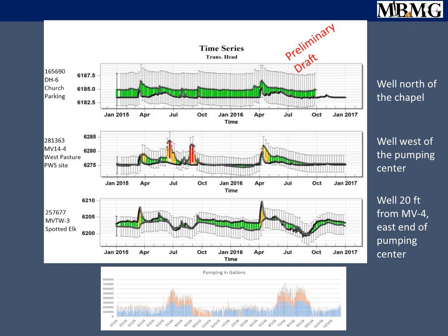Then down here in the lower one, you can see the impact of the pumping wells. When these wells are pumping high, it draws down water levels in the aquifer. But when you do the math on it, it's not drawing them out of sight. It's just stressing the system. But all in all, the system's reaching out to the stream.